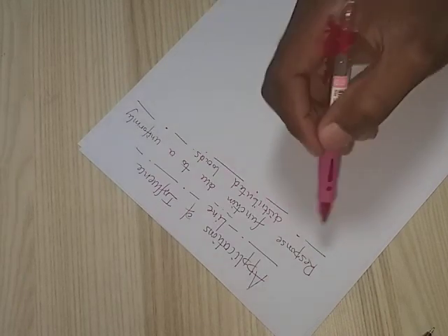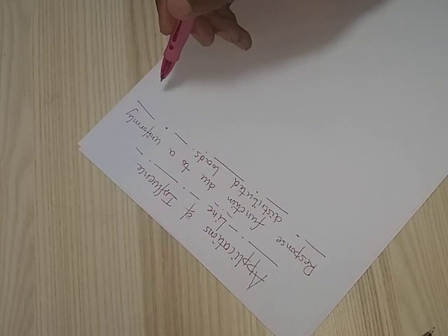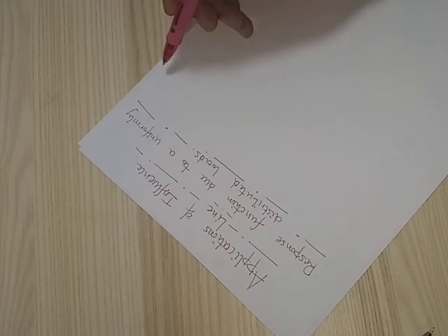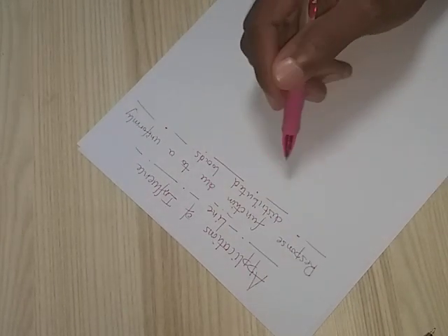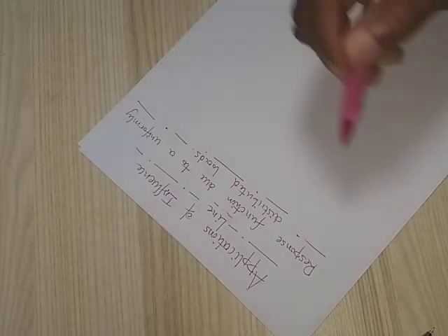We were talking about application of influence line last time, and today we're gonna continue talking about the same topic. Today we will talk about the response function due to a uniformly distributed load. Last time we talked about the response function due to a single concentrated moving load.